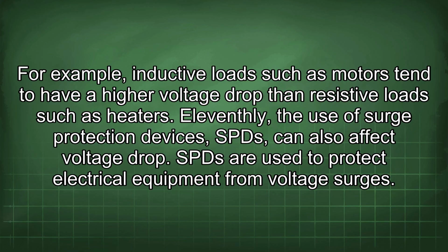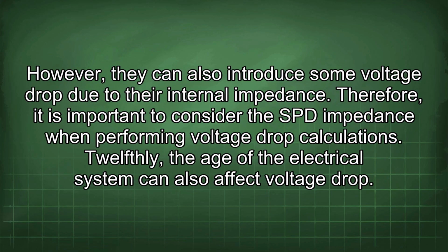Eleventhly, the use of surge protection devices, SPDs, can also affect voltage drop. SPDs are used to protect electrical equipment from voltage surges. However, they can also introduce some voltage drop due to their internal impedance. Therefore, it is important to consider the SPD impedance when performing voltage drop calculations.